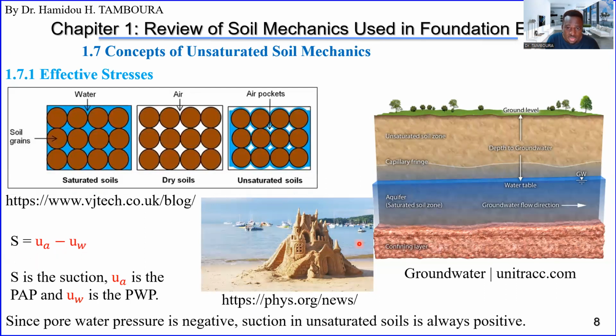Because of this suction, you can build this, because this suction is holding the soil particles together. So you can build to a certain height without collapse of the soil because of suction, actually. Okay, when you see this on a beach, please remember this.